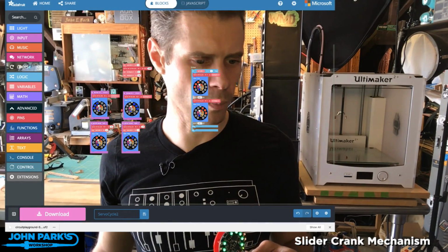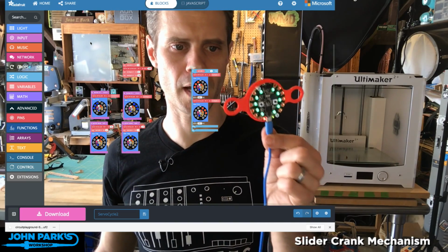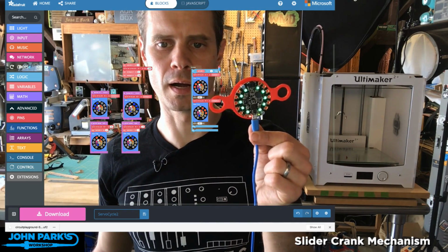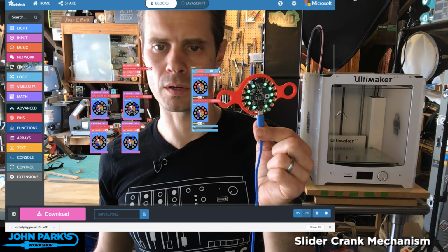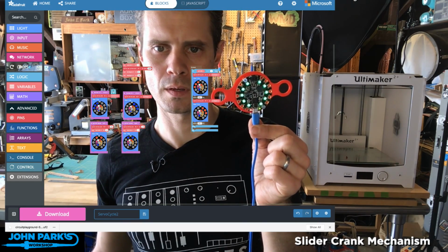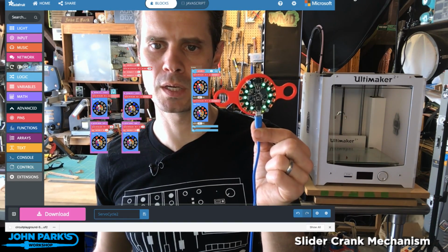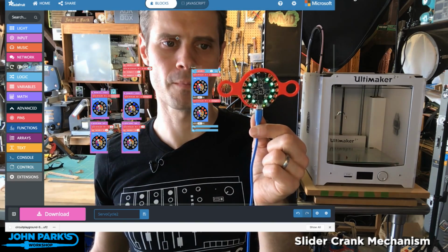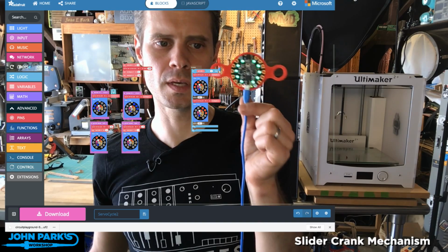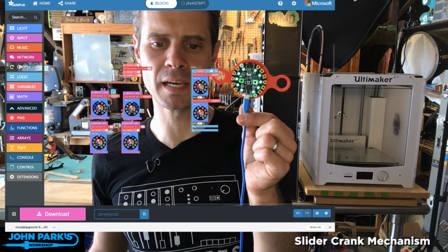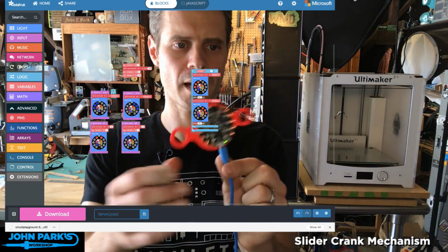And then you won't be able to see this just because I'm not opening a window to screen share that. But what I'm doing right now is going to drag and drop the file I just downloaded, which is called servocycle2.uf2. This is universal flash format. And I'm going to drag that onto this USB drive called cplayboot. And so when I drag that on there, it just flashed, it loaded it, and now it's ready.